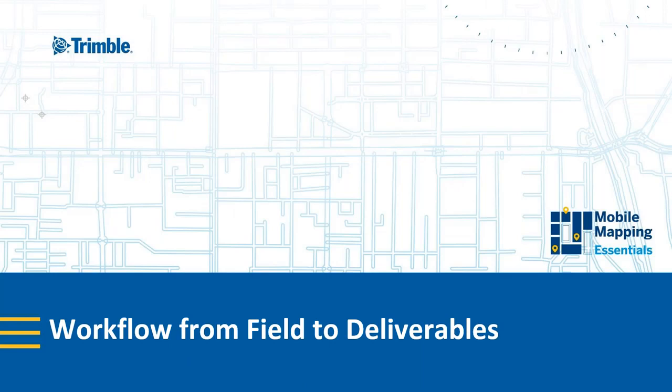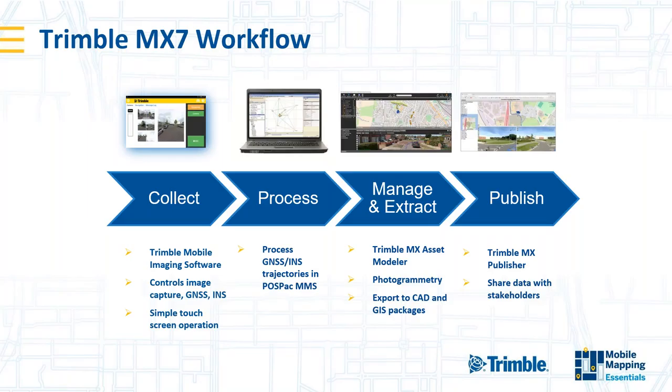So a little bit more now about what happens in the office. Once the data has been captured, what do we do next? So in Trimble, we have talked about already the section on the left, the collection part. The next step is to process the vehicle trajectory. We do this in a piece of software from Applanix called POSPac, which allows us to take that trajectory against a local base station and process the best trajectory we can down to the centimeter level.